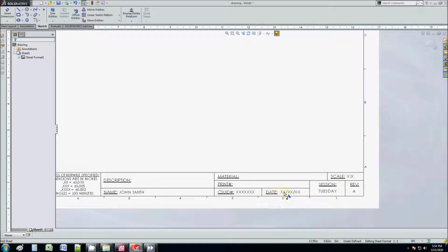So you have the date that the drawing was made, and then the revision. So remember, we talked about revision. Whenever there's a change made and the drawing was sent out, this revision needs to be increased. Now, in a lot of the older CAD programs, this has to be done by hand, but nowadays with a lot of PDM technology and Git control, a lot of this is done automatically because it's just silly to have to remember all these changes in just one shot.